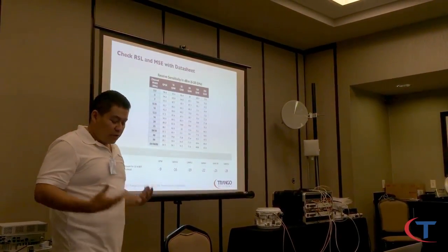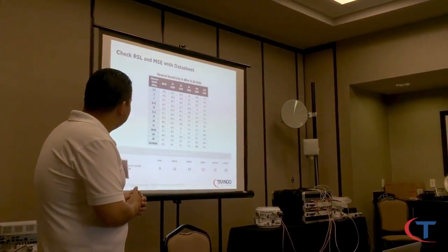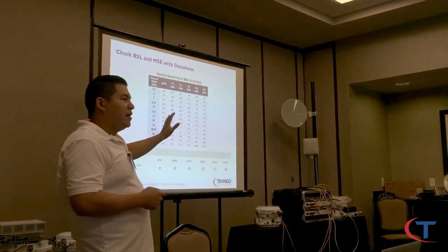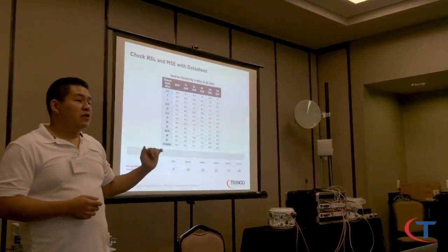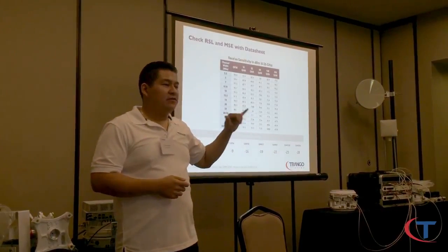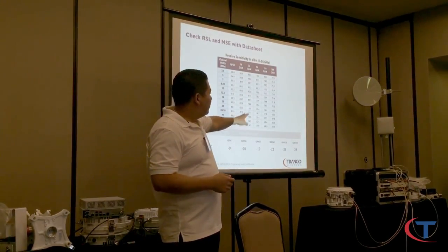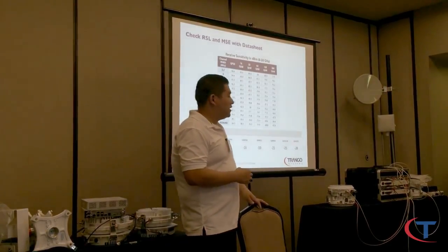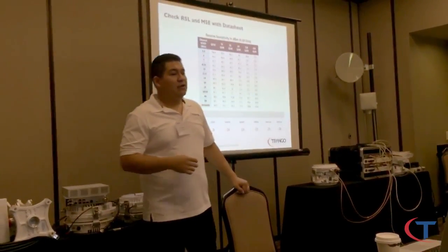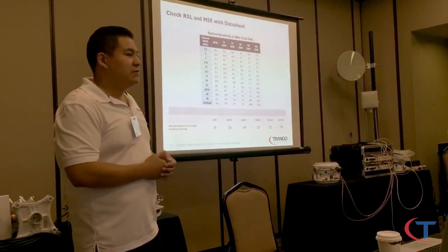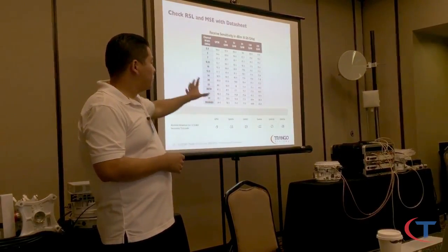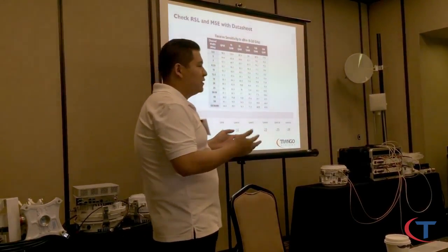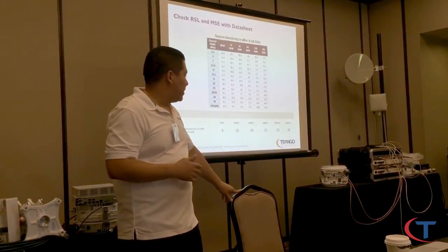Now the link validation, we're going to check the validation of the RSSI with the MCS modulation. This is not the best looking table, but we'll give it a shot. So, receive sensitivity. We've been talking about 1024 QAM link, and it's an MCS of minus 35.2. However, the RSSI is also really important because if you want to have a 256 QAM link at a 56 meg channel, the minimum RSSI you need to have is negative 65. Anything above that, you will not be able to get a nice 256 QAM link. So you need to make sure that your RSSI threshold is enough so you have enough space to actually withstand ACM going up and down.